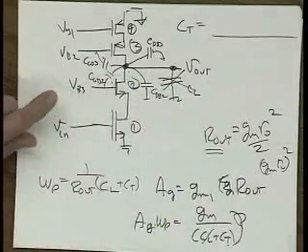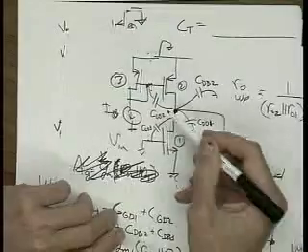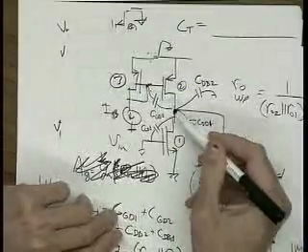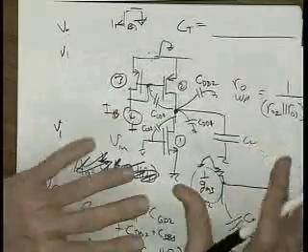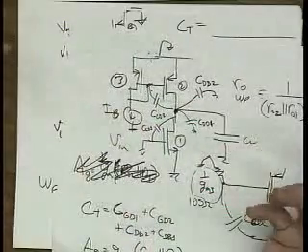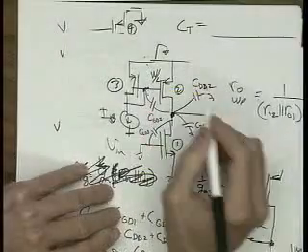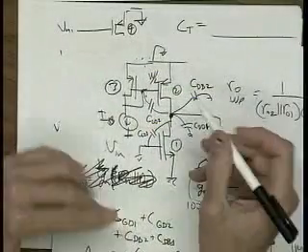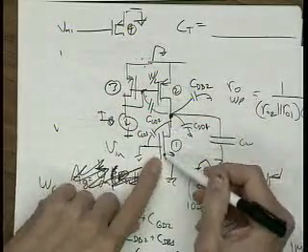Wouldn't that be different from your first circuit? Yeah, but it's still the same kind of capacitance, CGD, CDB, and so on. So it's the same sort of capacitance. Now, what can you change? Some things you can change are W over L. If I make the W over L of this transistor really big, let's make this one really big, because I want a large GM.